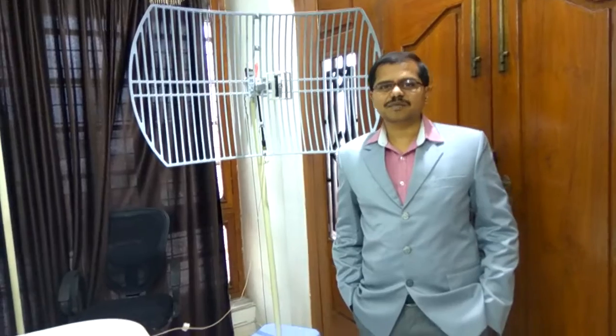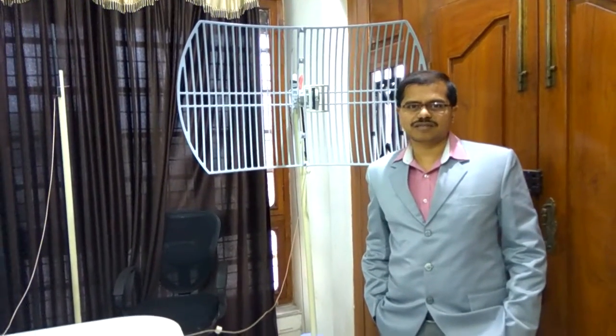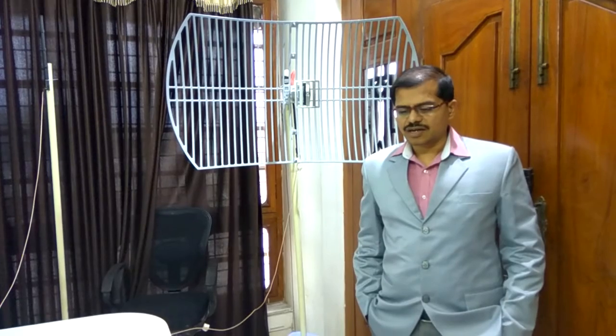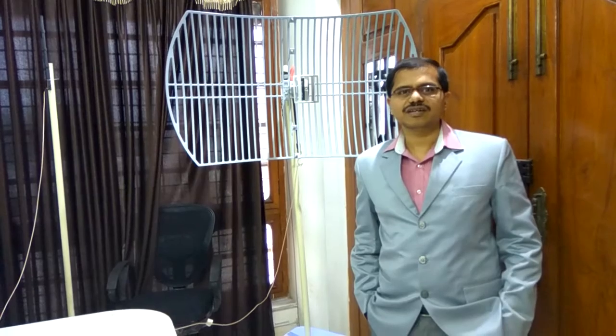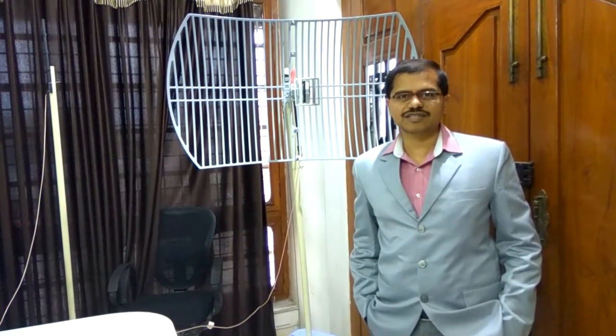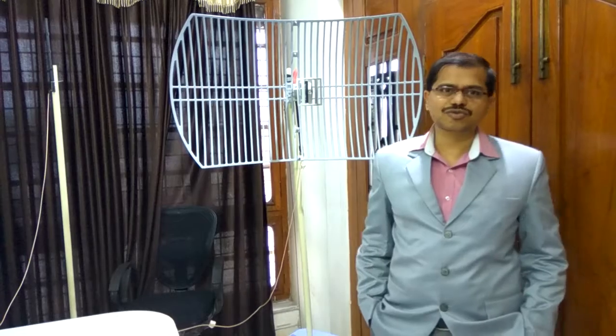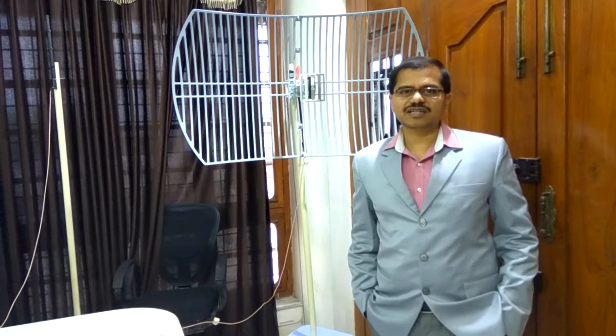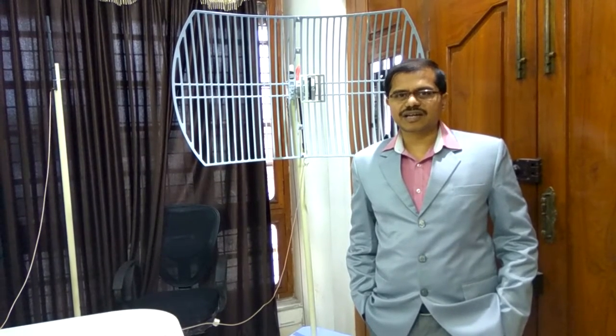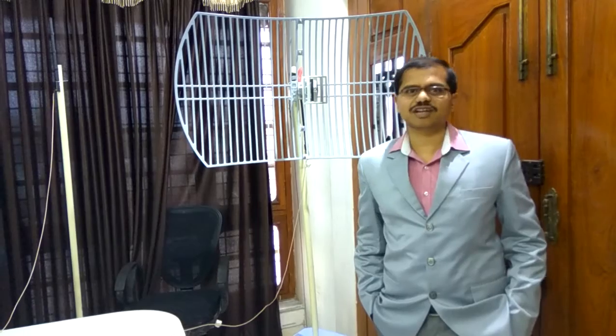Hi. Radar target simulator is one of the key technology areas for developing radar and radar based systems, especially in military applications when you require to test your radar at different target scenarios. Realistic testing in a field with actual targets is a very costly affair, and most of the time it is impractical to test. So a radar target simulator allows you to test your radar system under different field conditions, simulating the target, clutter, target swirling models, that is target RCS fluctuations, onboard jammer, and several features.